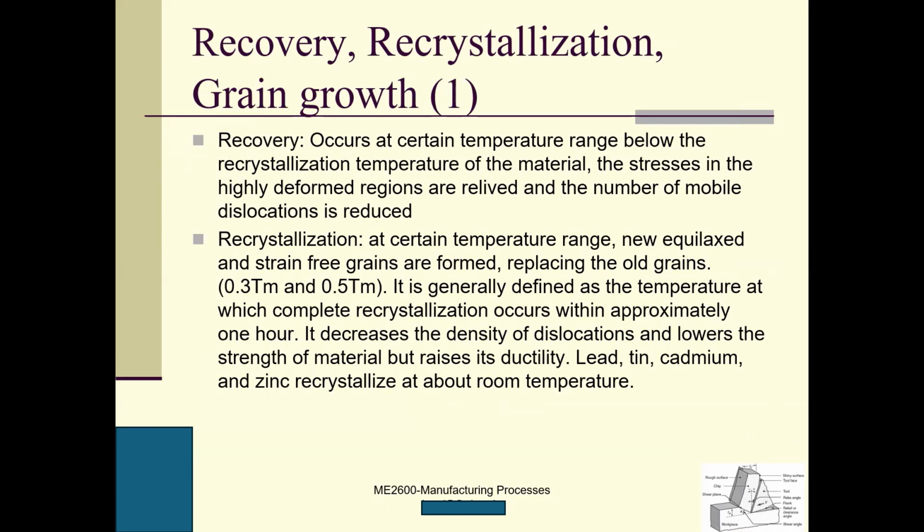You elevate the temperature, and these are three very, very important stages. The first one: after you finish cold working on this workpiece, you introduce some residual stresses, right? Then you elevate the temperature, so there will be recovery. Recovery means that the stress in the highly deformed region is relieved somewhat, and the number of mobile dislocations is reduced if you elevate the temperature.